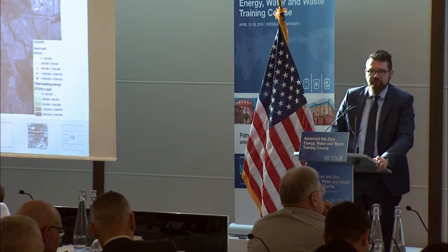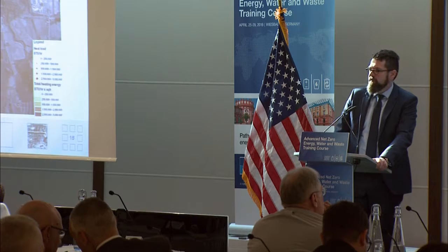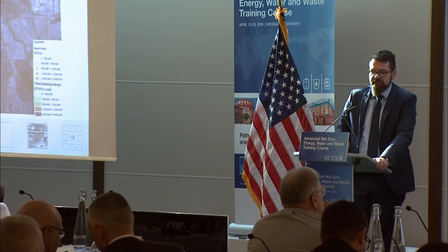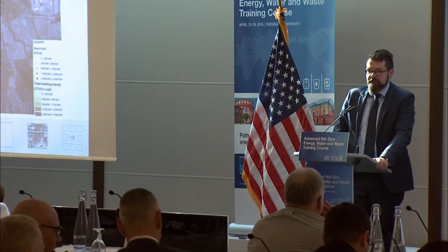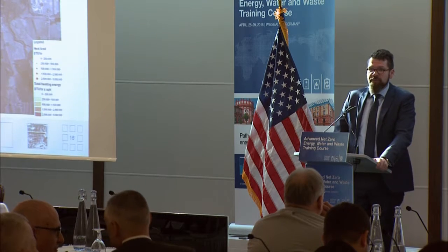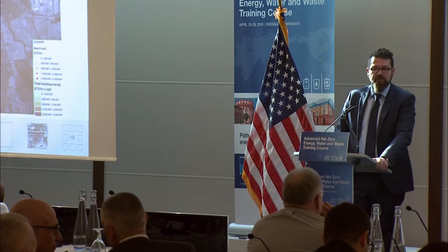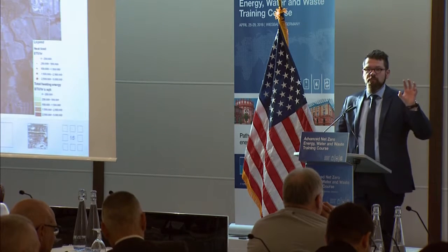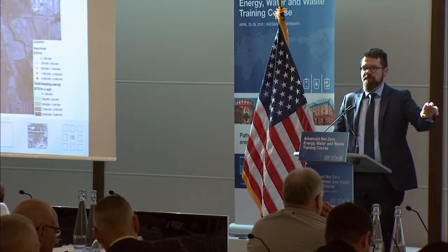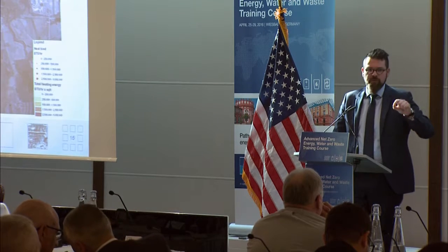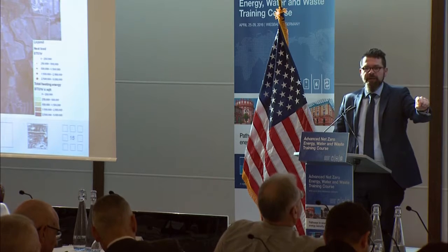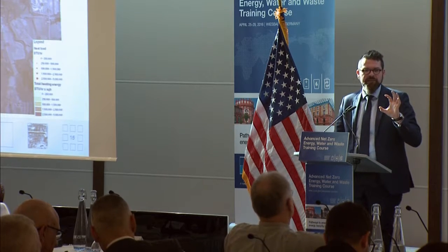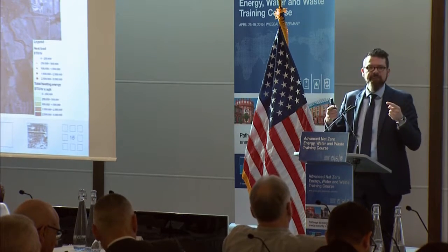There we have a square with a heat load which is a little bit higher than in the surrounding squares. This depends on one big user or one big building. So the idea behind central heating and cooling systems is to find one big building and justify, in terms of economics, the piping connection to that building, and then make it a little bit larger and try to connect the buildings on the way to that.